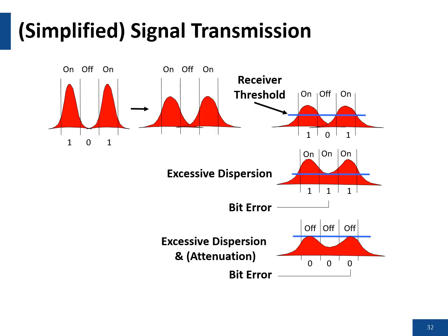So for example, a 1.544 megabit system is operating with a duty cycle, or the period of time between one pulse to the other, of 125 microseconds. The higher the bit rate, the shorter the amount of time between the duty cycles of the pulses.